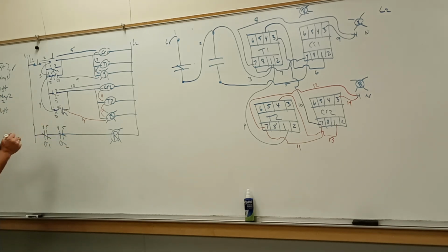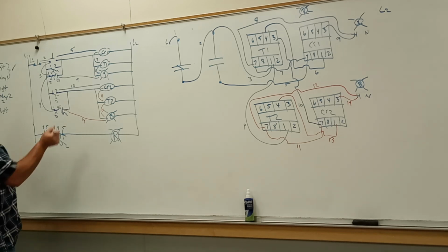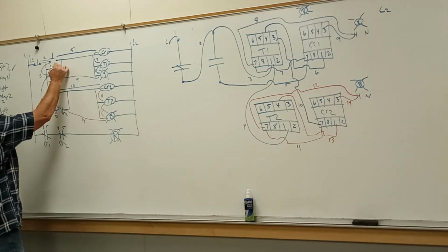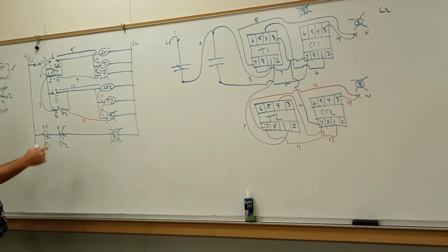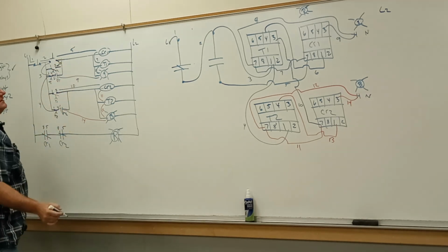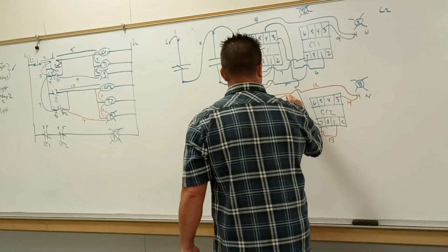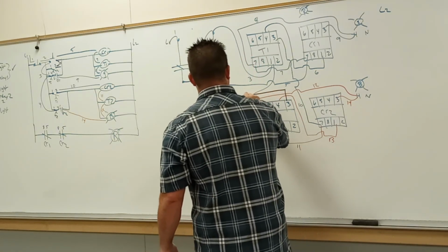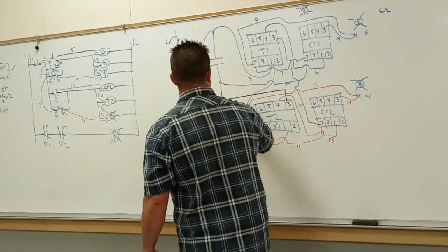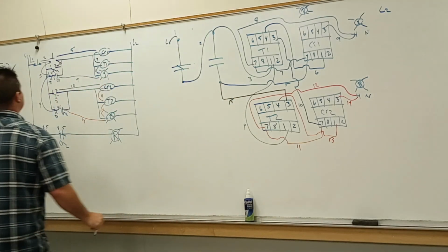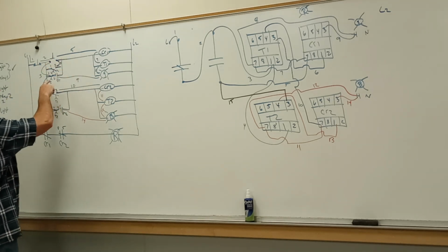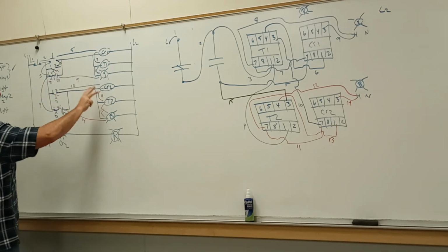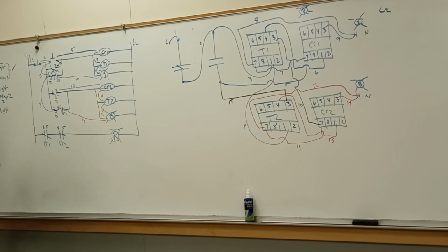So I've got that section. That seals, that's through, perfect. What's starting the process again? Now I'll go to my black pen, right here. Timer 2, number 3, and I'm going to run it right back to my start button. That will be wire number 15. So T2 number 3 right back to my start button, number 15. So now that's tied together, so it'll restart the process. I've got conductors between all of those points. Everything looks good. Now I'm down to just my red light.